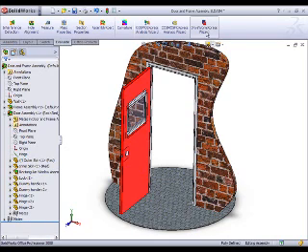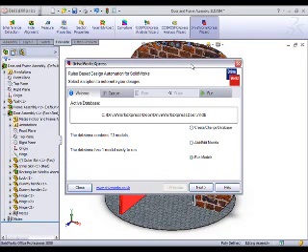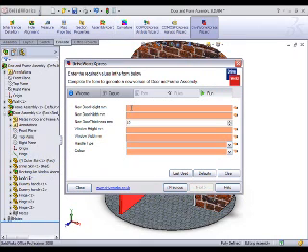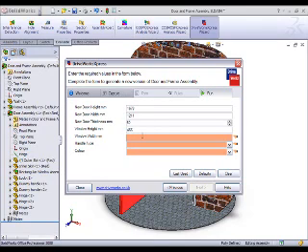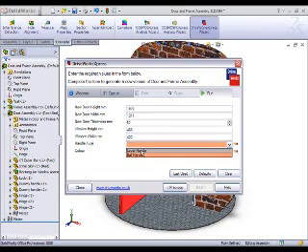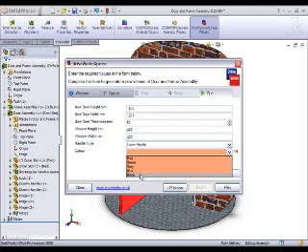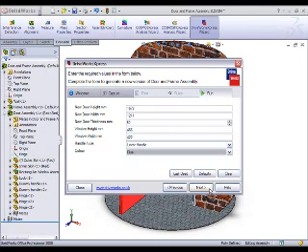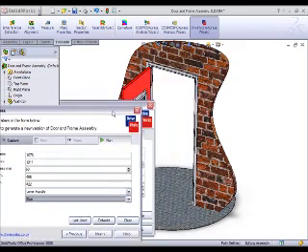So let's launch DriveWorksXpress and go straight to the Run Models part, hit Next, and we get the form that we created. We've got some rules in there saying these have to be within certain sizes, so let's start filling some numbers out. As we fill out the form, everything goes white to say we're okay, and the Next button's greyed out at the minute, so we can't proceed until we've got the right information in. So we'll pick a handle, pick a colour, let's go for blue, and just hit Next.